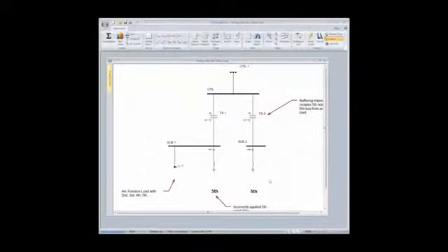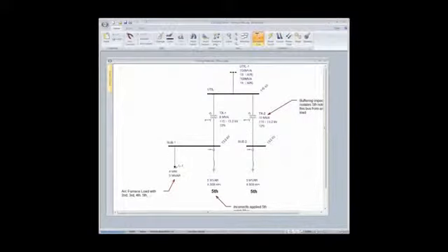So if we were to enter the harmonics focus and look at our distortion condition, we would see that the distortion on the voltage really isn't too high, but we're interested in power factor correction of this load. If we go back to database focus, you notice it is 5 megavars. So I chose to do that. I chose to put a pretty poor power factor on this arcing furnace.